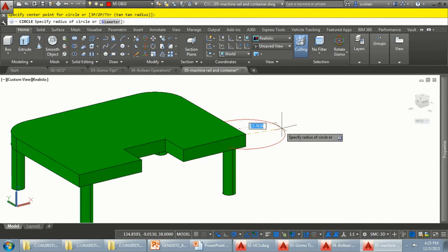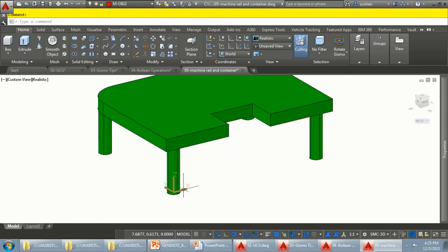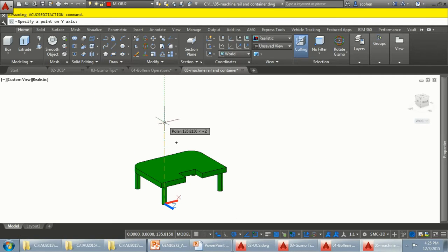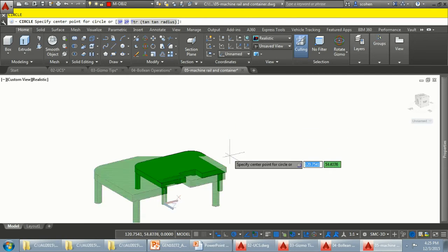So again, remember what I told you. It's drawing a parallel projection of the UCS, which is now at the WCS. So I do not have to move the UCS up here. I don't have to. There's no need. I can simply pick this, pick the y-axis, and just go straight up. Again, it's a parallel projection of the UCS. So I'll just start the circle command.